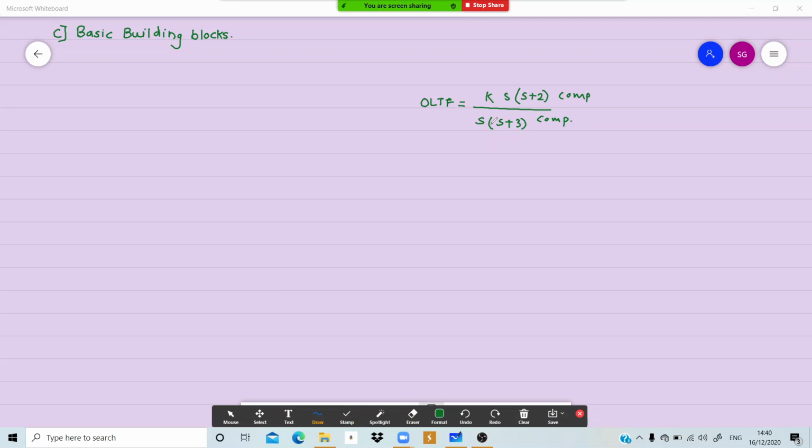Except this, nothing is going to be there in your system, right? So we'll consider these as single blocks. We'll try to find out what their individual graphs are. After taking log, definitely you are supposed to add them or subtract them. So you will put all these things on the plot, you will add or subtract, and you can have the graph of the OLTF. And this is the basic idea behind the Bode plot, right?